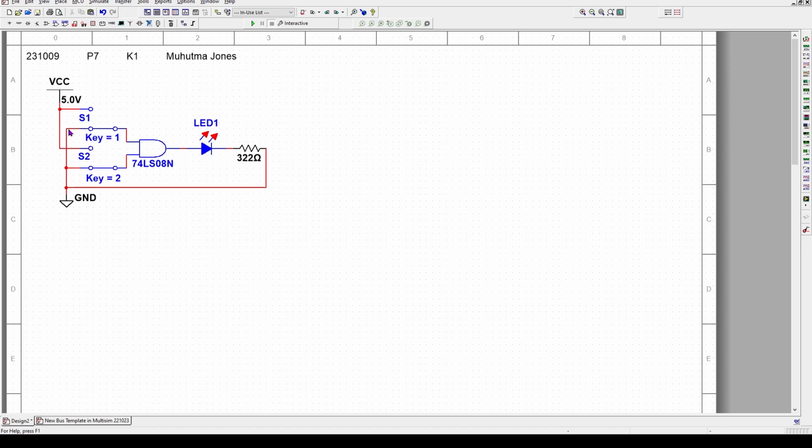These wires that cross each other are not connected. These wires are connected, and it has to do with that little dot. And you might have seen schematics show a little bridge over them. That's not what Multisim does. They show the dot, and the dot means they're connected. And if there's no dot, they're not connected.